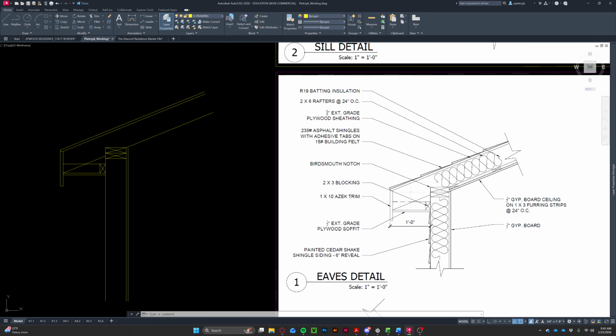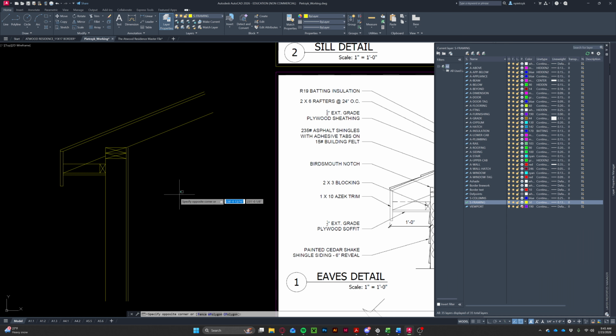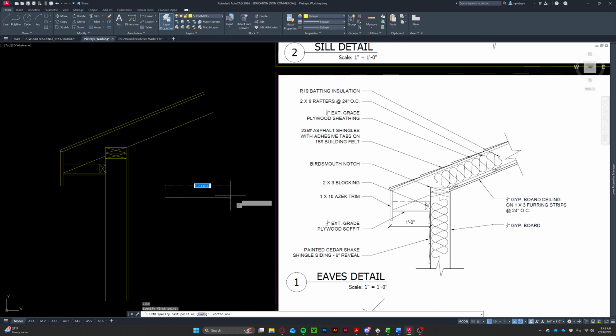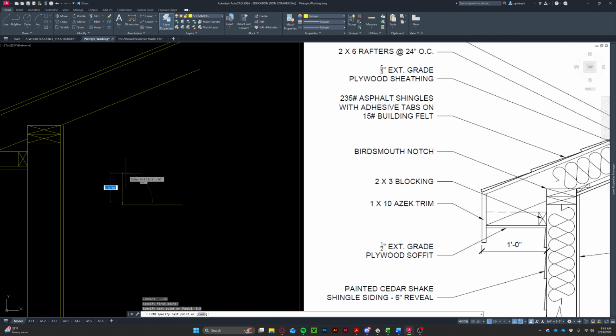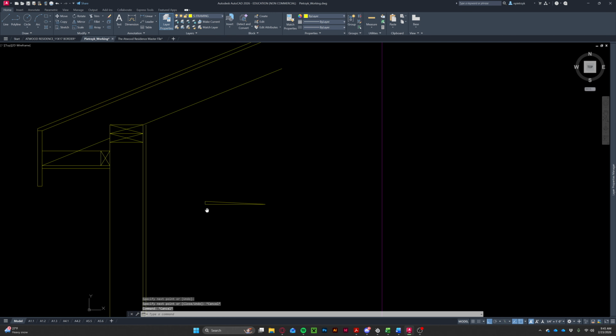Cool. Now, these shingles on the roof, they're 10 inches long. How do I know that? I just do, but you can also estimate. It's not the biggest deal in the world. How we're going to draw these is very simple. I'll draw a line horizontally 10 inches long. On the left side, I'm going to draw up 0.5 inches. Maybe a little more if I'm feeling a little spicy, but 1/2 inch is good. And I'll connect them up to create this triangle.